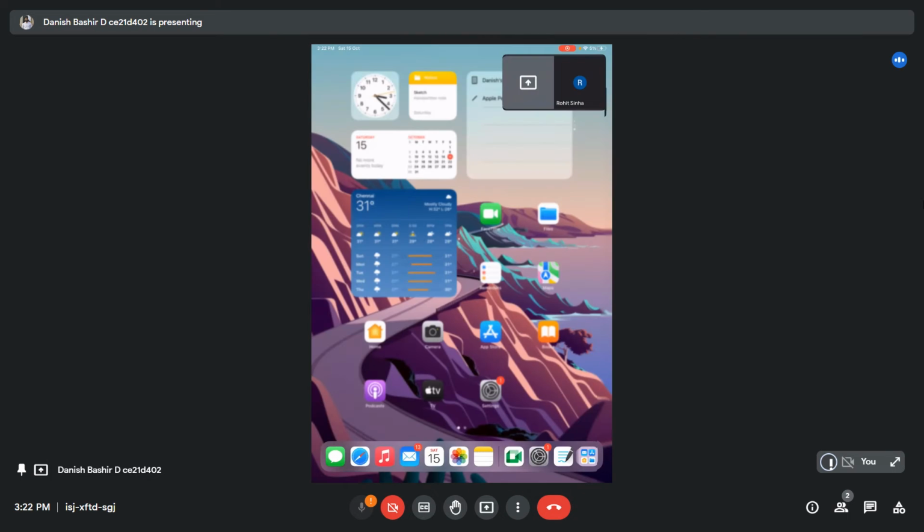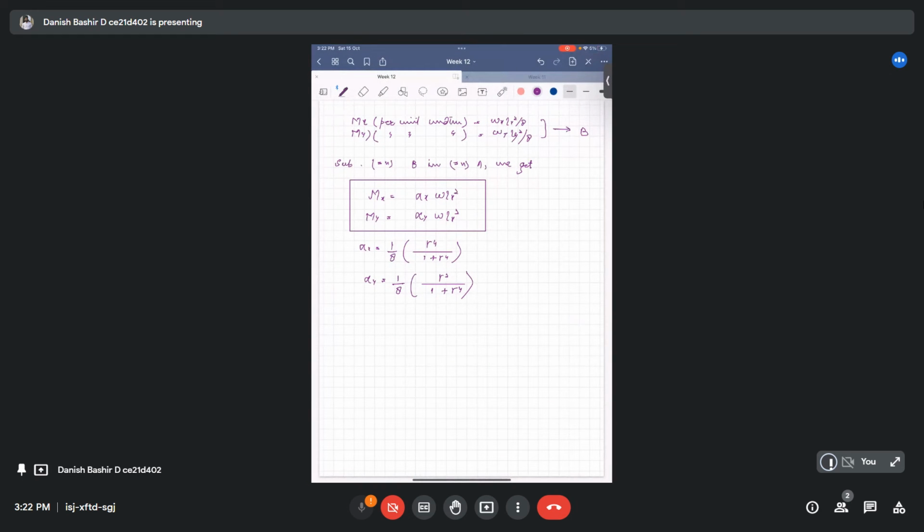We have these two moment coefficients. So what we get by doing this formulation is that both the moments Mx and My given by this equation c are in terms of span Lx. So if we have the short effective span, we can get both the major moments acting on the slab, and we can design the reinforcement based on those moments. Okay.